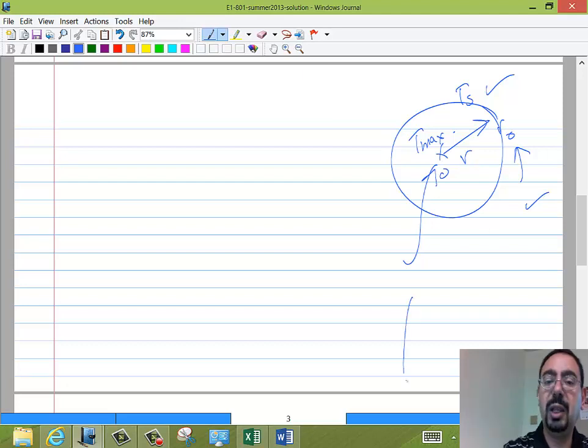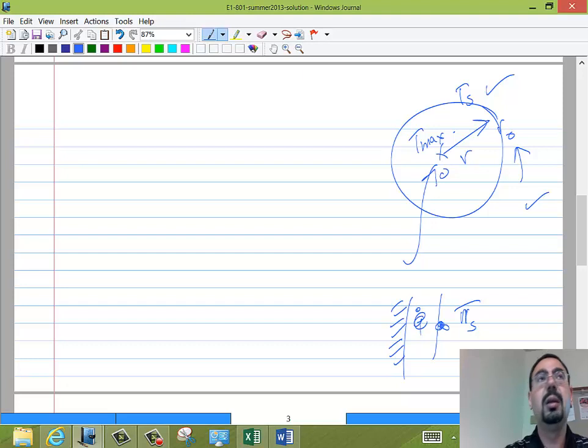It's as if I'm telling you there is a wall insulated from one side, and it's generating Q dot or E dot per unit volume, and here is Ts, and find for me the temperature distribution. Well, when you integrate this twice, there is no place to get the boundary condition except at the two edges.